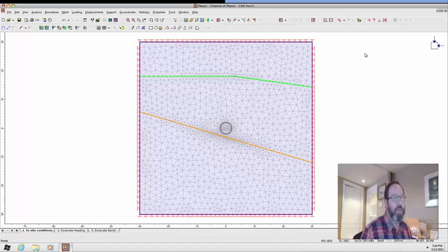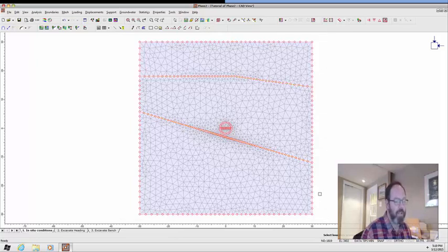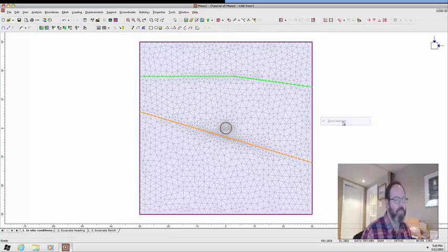There's another type of boundary called a roller boundary that we can use. Let's get rid of all these boundaries here by clicking Free Restraints, and then we'll select everything and say Done. Okay, so there are two types of roller boundaries. First, an X restraint only. We'll click on all of these three segments and push Enter. Roller boundaries means it cannot move in the X direction, but it is free to move vertically.